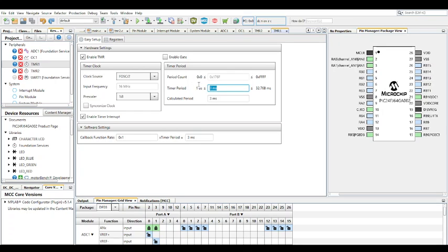And then timer 1 is essentially for the loop execution times. This is basically a timer interrupt. So your PID control loop algorithm is going to occur every 3 milliseconds in this case. Of course, you can make it as low as 10 microseconds theoretically, but with this microcontroller, from what I checked, you could go down to 130 microseconds, but safely with a proper PCB, I'd say take it down to 200 microseconds and no more, for it to function properly. You want to give yourself some breathing room.